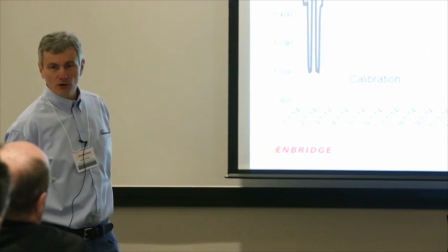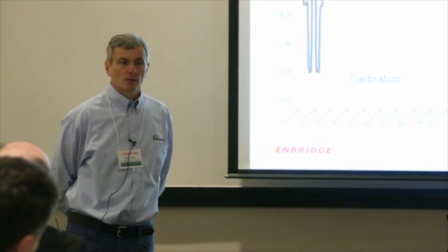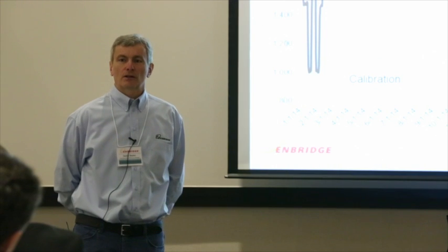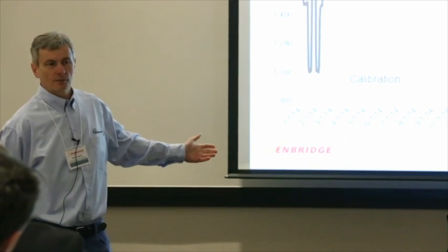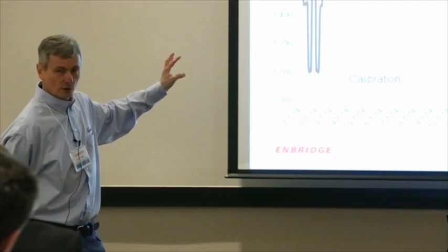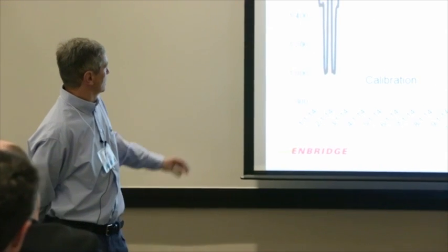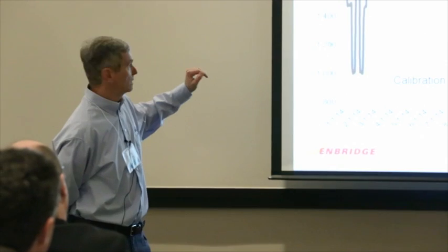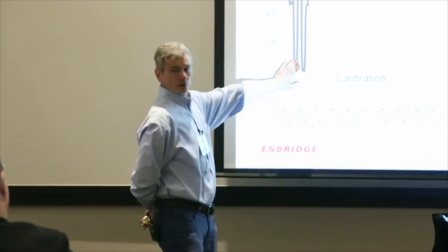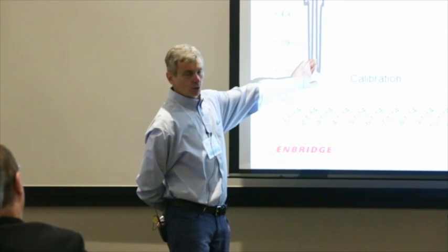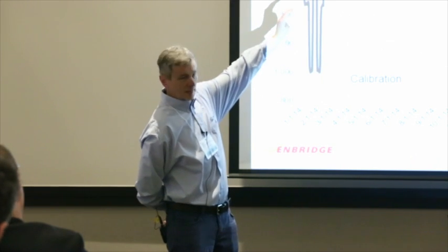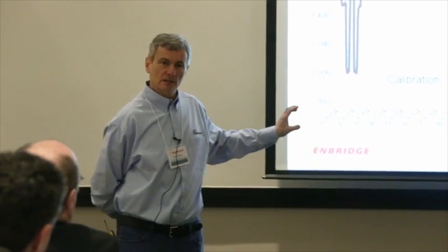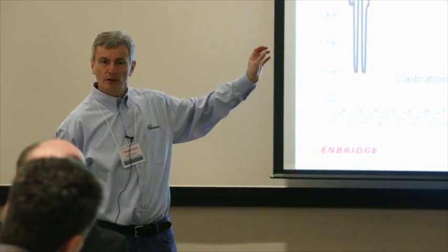You will go through a period of calibration. You will install the meter, and then it will be like, wow, this is not what I expected. Oh, the wire is not in. Oh, wow, my factor is off by 2. That's normal calibration. So you'll go through that period, you will find out what works, what doesn't. Then you'll start a fairly stable period, and you use that for baselining. You don't want to baseline over here because your baseline will be worthless. You want to know that your data is valid, and you want to know that the data is stable for a little bit before you do the baseline. Energy driver: if you have an energy driver that's seasonal, this baseline must extend much further than this one.